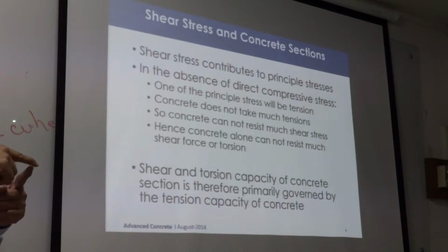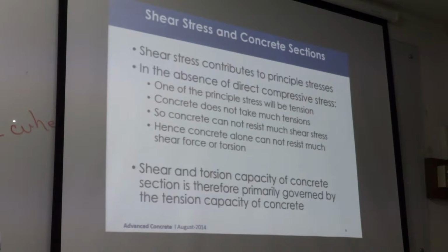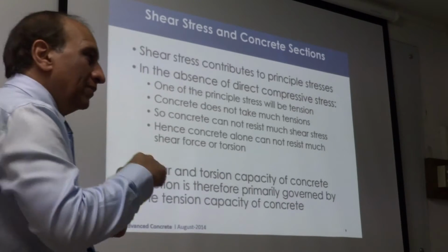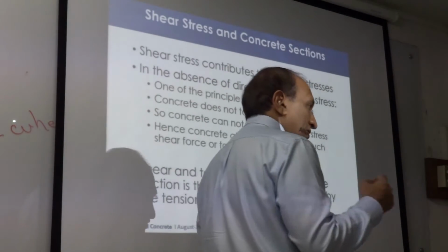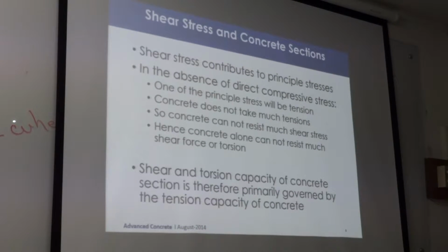The one pointing to the minimum, or minus, becomes the other principal stress. So maximum and minimum stress directions and stress values in a section become principal stresses, and they are always perpendicular to each other, right? And one of the properties of the principal stresses is